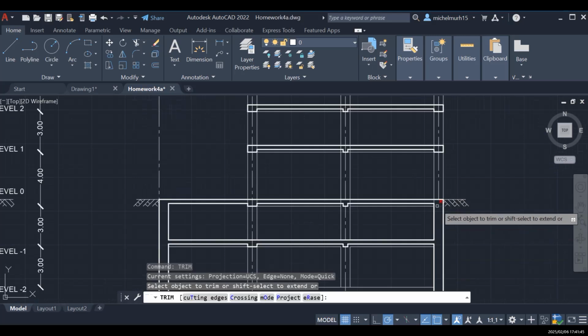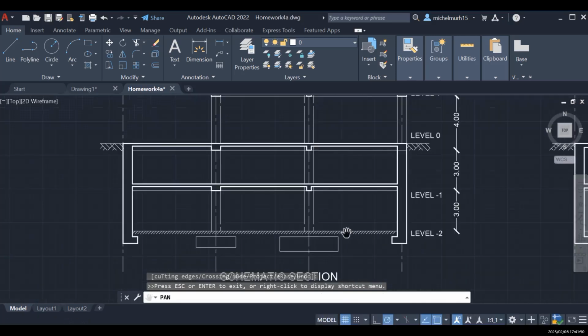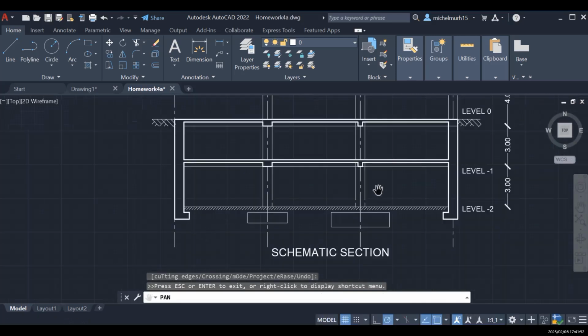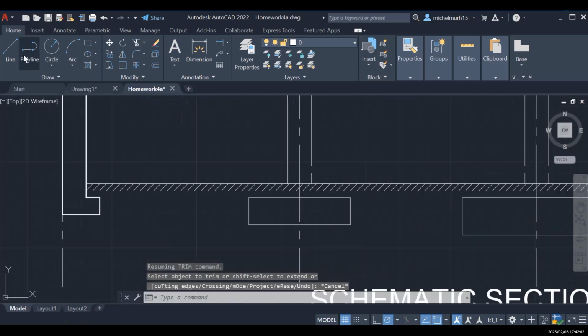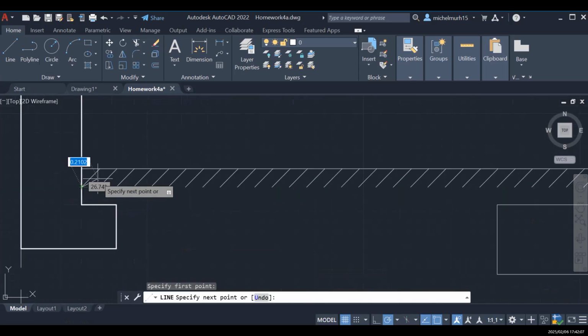I'll trim this line. All right, and for the last part before the dimension, let me show you how to indicate this inclined line. It's just simple. You just need to use the offset. Like if you create one, let me just open one here. I'm gonna show you. Let's see the angle. The angle is 45 degree. And then the height is 0.2967.